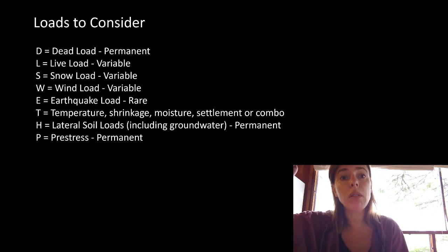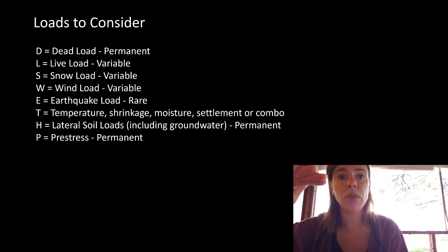What if we pulled on that with 2 kilonewtons? So we've got 2 kilonewtons trying to put it in tension. Applying 1 kilonewton of compression means at most we'd still have 1 kilonewton of tension. So we can manipulate a system to apply a tension force that is greater than any compression forces we would ever see applied to the system, and we pre-stress it for that.